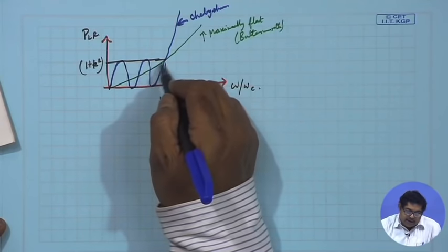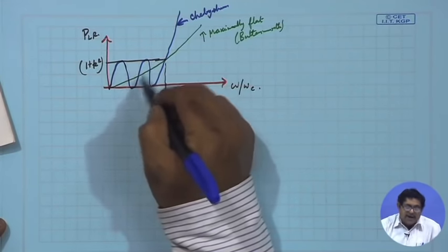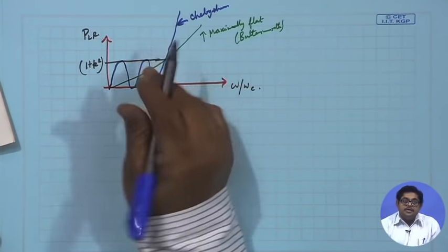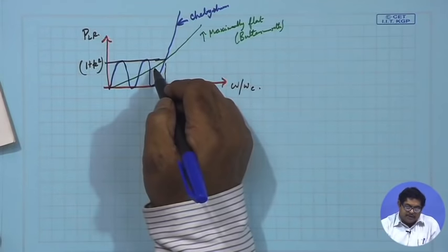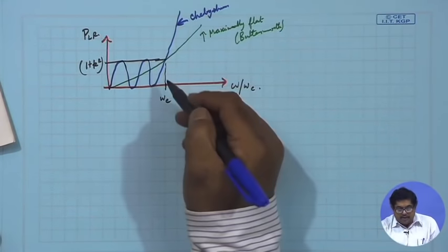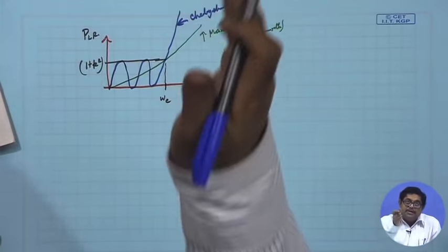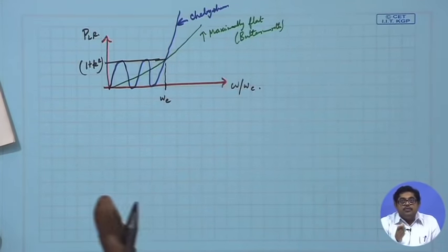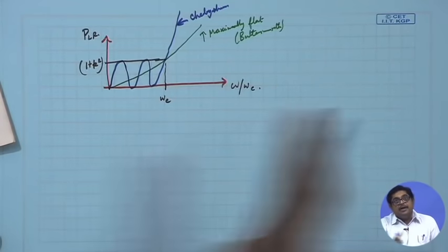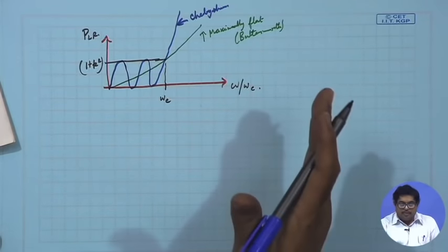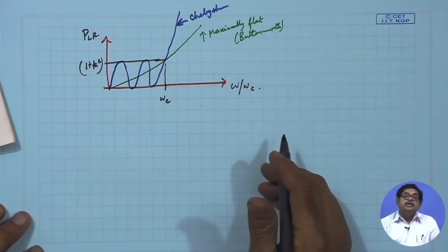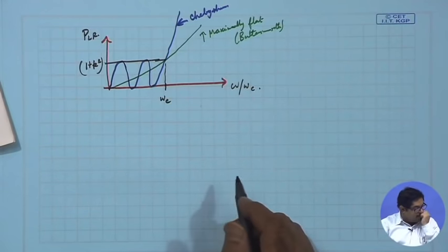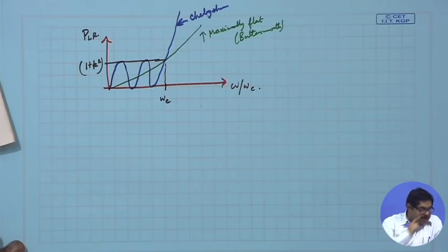You see that here it was monotonically increasing, here I have ripple, but I can specify that it be within this limit. So, in the pass band it is never crossing this limit. Once it is going away from the pass band, it is much sharper than Butterworth, that is its advantage. So, if your prime concern is, after the pass band, when I am entering the stop band, that you have a very good and very sharp cutoff, you opt for this Chebyshev polynomial.